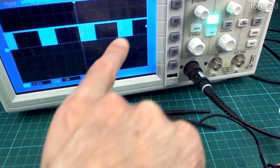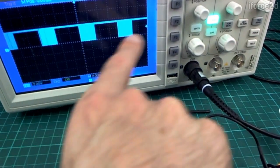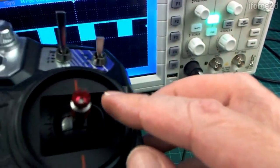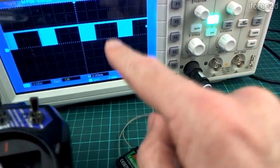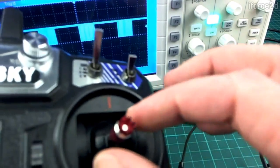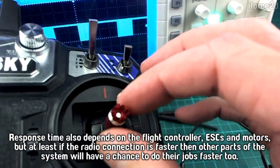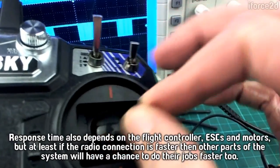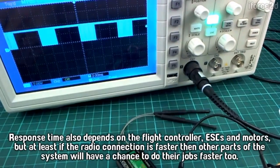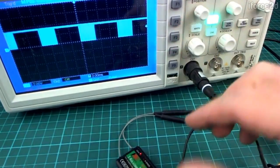So it's about 8 milliseconds between sets of pulses, which is more than twice as fast as what we were running before, meaning that when you make a stick movement, this will be around 120 times per second that your stick movements are going to be updated in the flight controller. So immediately we can see that we're going to get a faster response time when we move. And with the speed that these quadcopters can move, you really want to have a nice response time when you're trying to control it. So that's one advantage of a serial connection, ibus in this case.